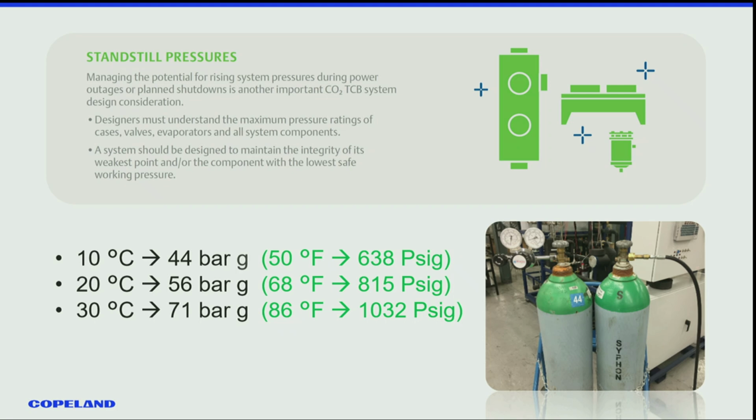So that's something to consider. Those tanks sitting here right now at the back, they're sitting with 815 pounds in them. So that's also important when you go to charge a system that's got a 650 pressure relief. Be aware that you don't want to crank that valve open too wide because you'll blow your pressure relief, at least starting off the charge. As more refrigerant comes in, it cools down and it lowers.